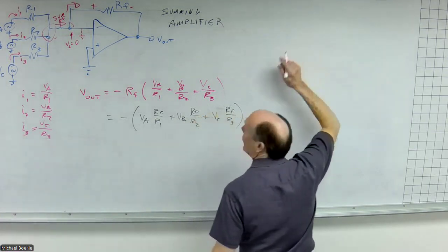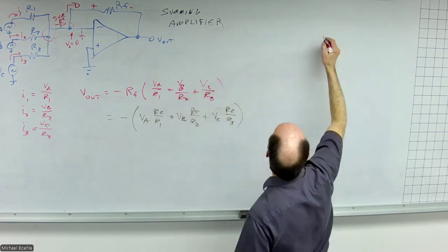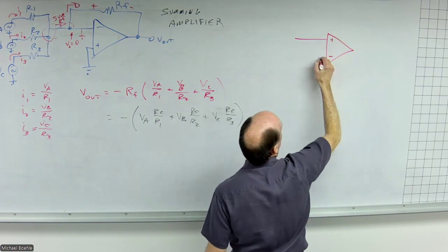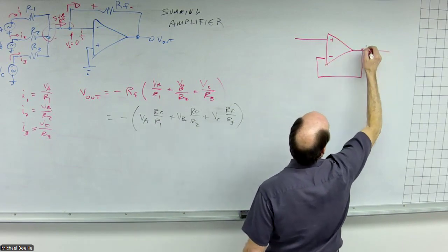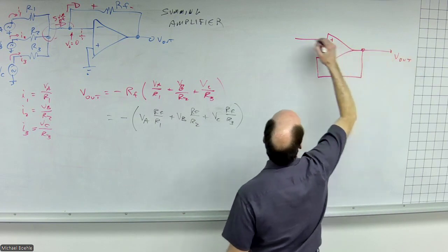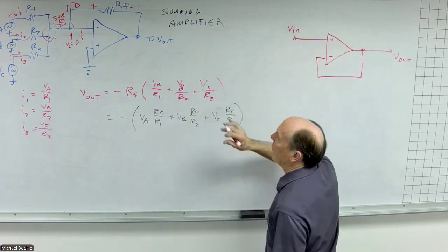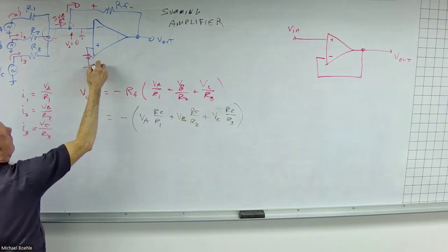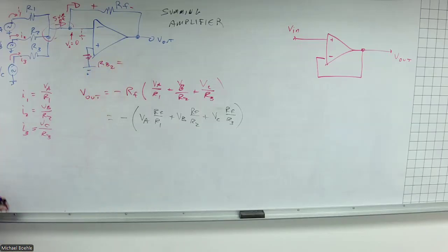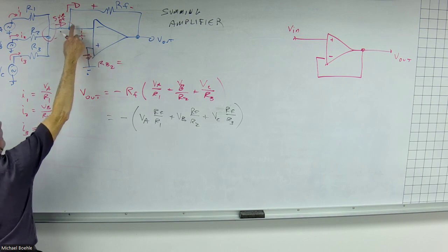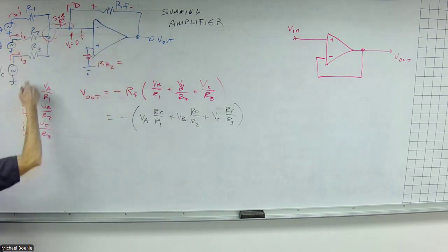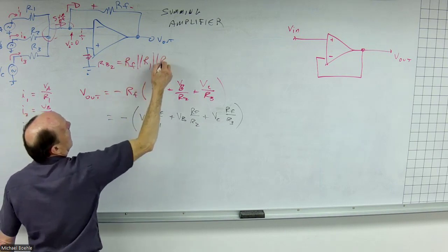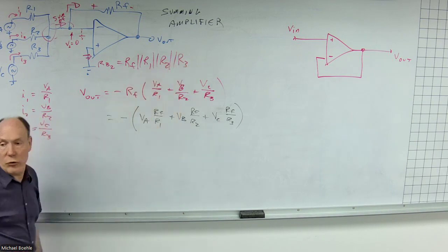All right. Lastly, we do a modification of my non-inverting amplifier. Fairly straightforward here. Well, actually, one other thing here, right? No resistor here. If I want to add a matching base resistor, looking back from the other base, I have RF to ground, R1 to ground, R2 to ground, R3 to ground. So basically it would be the parallel combination of all of the resistors used.